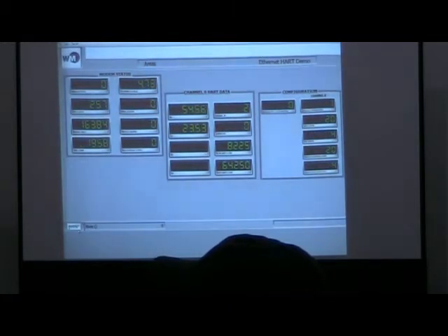We are planning, in the next 2 years, a migration plan to bring some of that data in. If we build a pipeline that's going north, one of the requirements is to have HART over Ethernet back to our system so that we can monitor the instruments that are out there. So if we can troubleshoot and identify the failure in advance, send somebody out there, we can tell them exactly what the failure is.